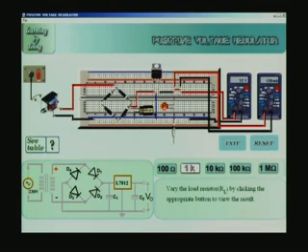If I change the resistor, I can use different load resistors, and you can see that correspondingly the load current also changes. So this measures the load current, this measures the output voltage across the load, and you would find the voltage remains constant at 12 volts for different values of resistors that I have. And as I already mentioned to you, this IC regulator is also short circuit protected.